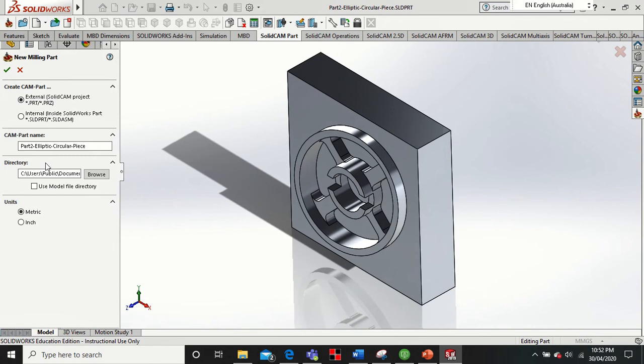This involves deciding the size of the tool and the material that the machine is going to be interacting with, all relatable to the RPM and feed rate. All this because when you go from rough cutting to finishing cutting, the RPM increases and the feed rate decreases to obtain the desired surface finish.